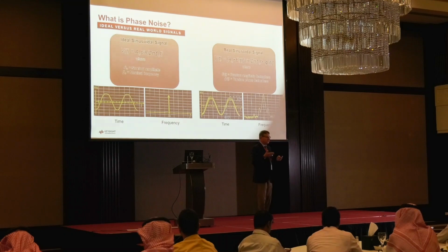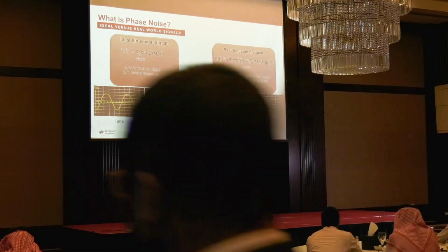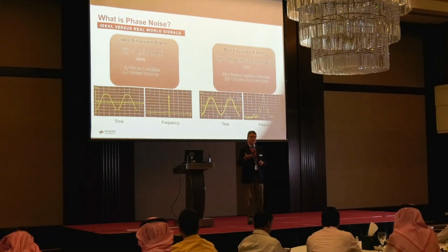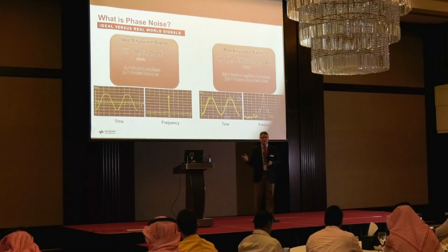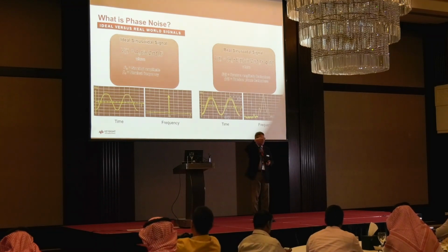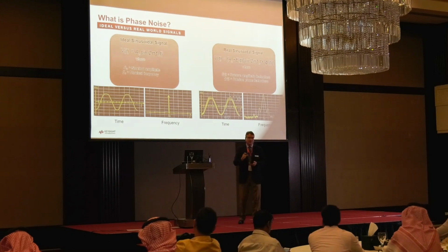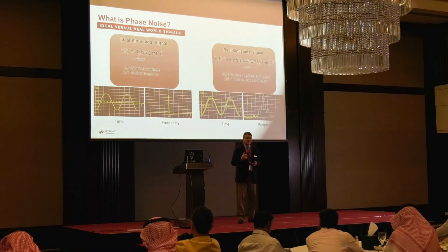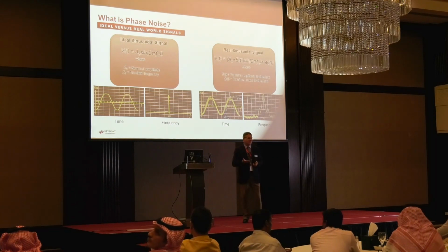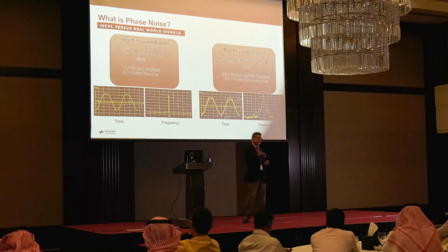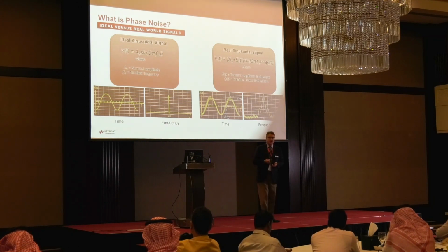But in the real world, we know things are a little bit different. We have noise, and there are actually two kinds of short-term noise that can be associated with that signal. There is amplitude noise, which shows up as an amplitude term, and you see that on the time domain graph on an oscilloscope, with some changes in amplitude fluctuating randomly about a nominal value. And then there's also maybe a change in the sinusoid itself on the x-axis. So that's a change in phase or a change in frequency. Actually, the frequency is the first derivative, the change in frequency of the change in phase.